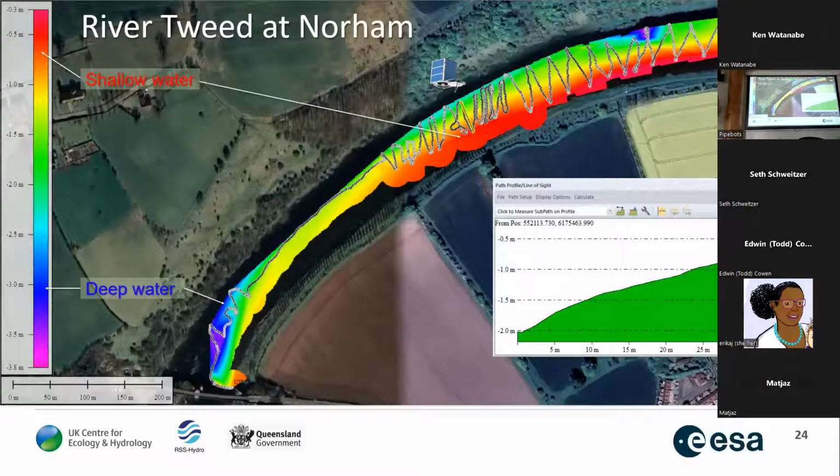So we went back later on. It was only after the fact, when we'd gone home and got these videos and processed them, that we went back to do some bathymetry mapping, so we could retrospectively calculate discharge based on the velocities that we got. Here's about where it was. And so we could work out the cross-sectional area. We'd got the surface velocity, we used the surface alpha, we could calculate discharge, which we could compare to the measurements that we made down here with our drone and our ADCP.